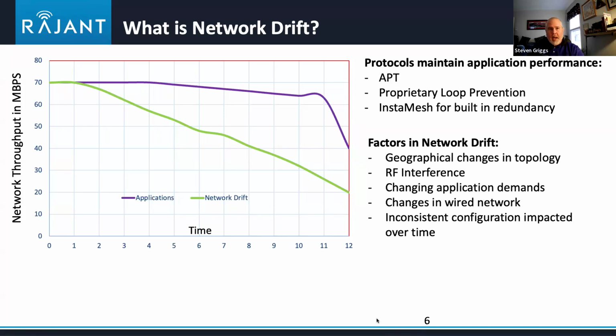Now, I kind of liken it to the death of 1,000 cuts. What happens is over time, you have trailers that go down because of solar panels that are not getting charged anymore. You have misconfigured radios in haul trucks that are no longer really reporting well to the fleet management system. You have physical issues like busted antennas, ingress RF cable, things like that.